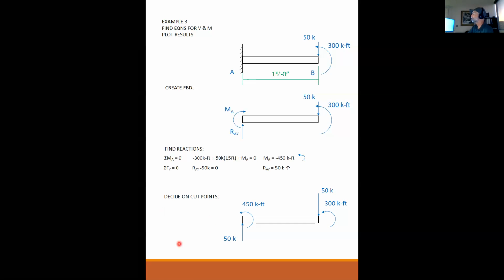Okay. So remember, this was minus. So now that I know that the direction is counterclockwise, I put it as counterclockwise. This one, I know the direction is up, so I put it as up. Don't put minus 450 here. You just hopelessly confuse yourself. Just put the magnitude and the direction that you found from this step here. Okay, does that make sense to everybody?